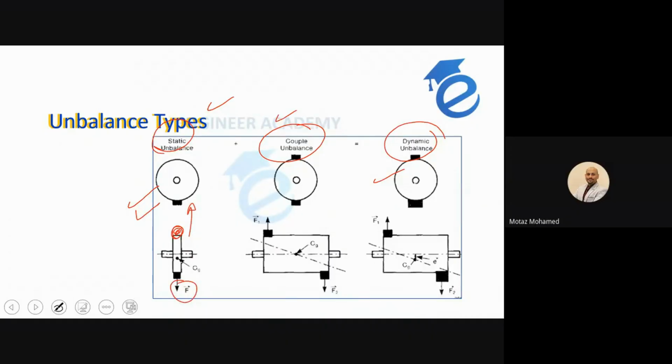But it's not that easy because you don't know exactly where the unbalanced mass is. Here you can see clearly because it's drawn in this graph, but in an actual case, it's not like this. In an actual case, if I have a rotor, normally the density here is different than here, than here, and each part gives centrifugal force. What we're dealing with is actually the equivalent forces. Then it's very important when you go for balancing, you need to decide exactly what amount of mass you need to add, and when and where.